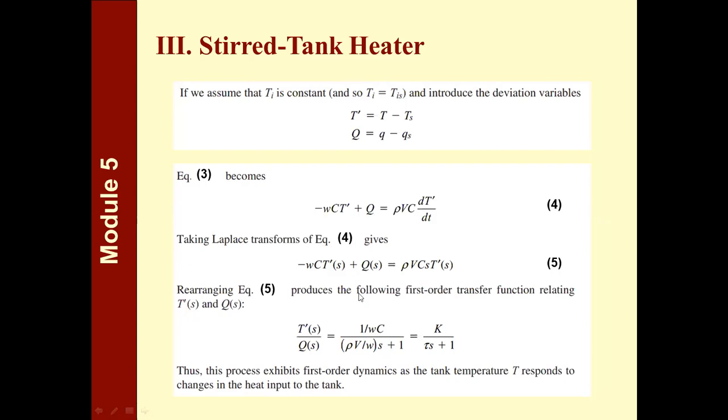Now, if we take the Laplace transform of this equation, we have this. And if we rearrange equation 5, we produce the following first order transfer function relating your T to Q. As I have mentioned, it's assumed that there are no changes in the inlet temperature of the fluid entering your tank. If it's the other way around, if it's the Q that is not changing and the inlet temperature that is changing, then your transfer function this time will be relating T to T sub i.